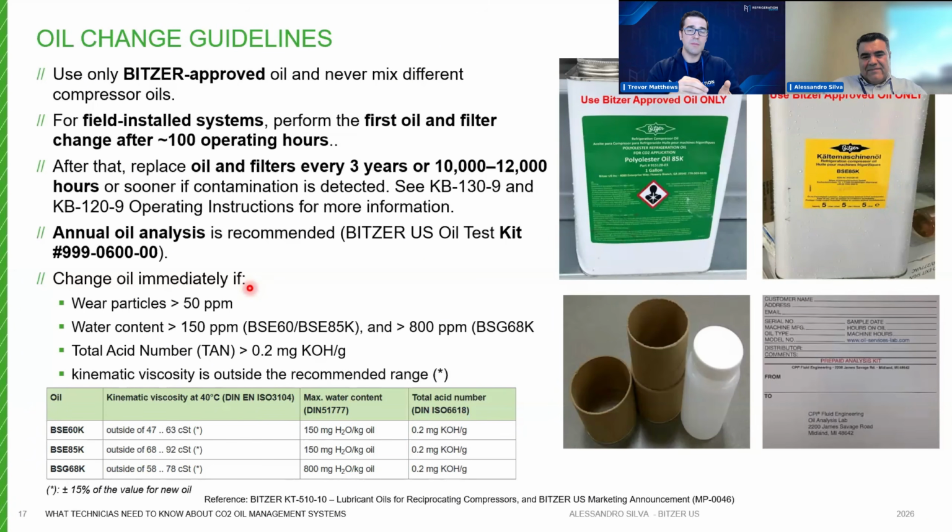Oil is expensive, but this is the conversation a technician, and your company, needs to be having with the customer right away. So the expectation is there, and they understand every 2 to 3 years we're going to need to do this. Because when you get to 5 to 6 years, these compressors, it doesn't matter the manufacturer, should last around 15 years. The life drops dramatically when you're not changing this oil.